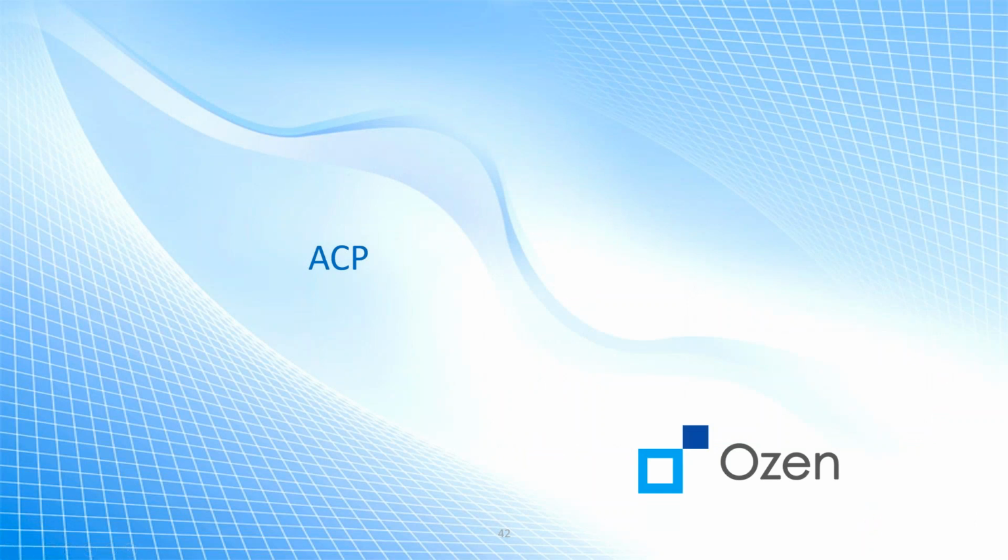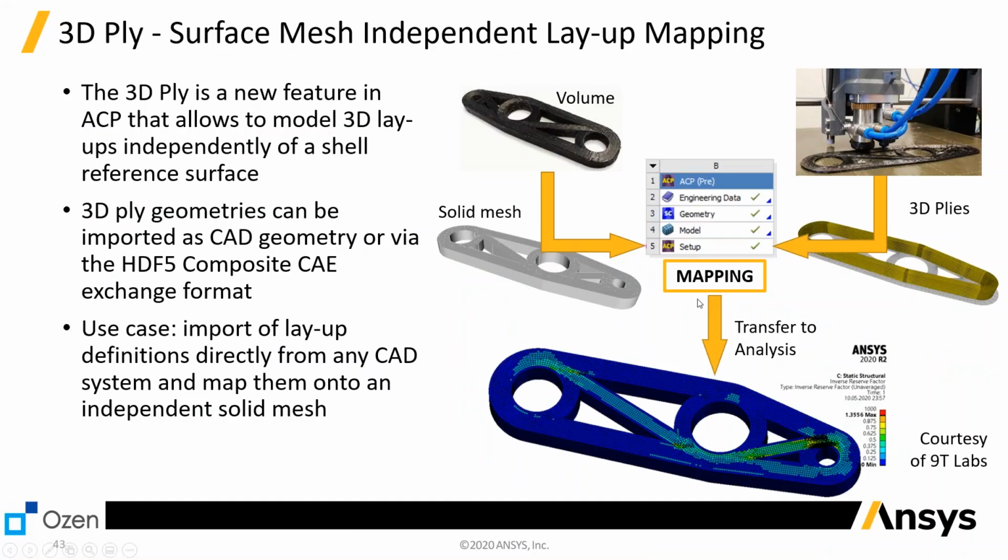For the ANSYS Composite PrePost, there have also been different modifications, mainly related to 3D ply surface mesh independent layup mapping. Now you can import the geometry of the 3D ply, the new feature, which allows you to define layups independently of the shell reference surfaces. Like we can check here in the case, you can import layup definitions directly from any CAD system and map them onto the independent solid mesh.